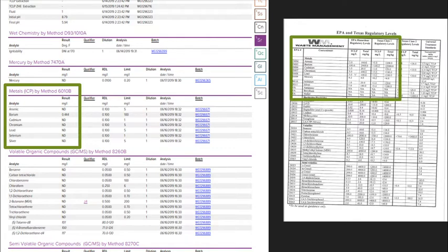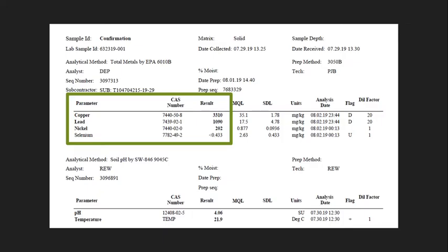So arsenic says ND, which is for non-detect, which is a good thing. That means there was none detected, so we're good there. Barium says 0.444. Well, we go over to the right side, barium, under TCLP, it says the hazardous waste limit is 100, which obviously 0.44 is way under that. And then if you look at all the other numbers, cadmium, chromium, lead, selenium, silver, those are all non-detect. So this is non-hazardous waste, so yippee, we're good.